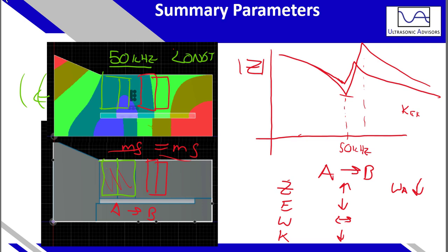But that being said, if you put your piezo here versus here, the static operation will still be quite similar. You will still be pulling against the center bolt when the piezo expands. It's going to pull the center bolt along with it. It's still going to do very similar work against the system at off resonance. So it's a way to perhaps compare those results.